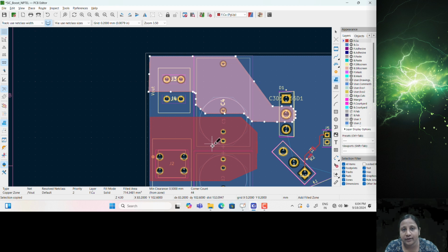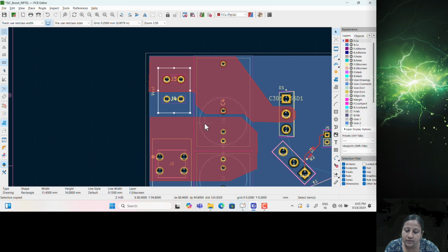In a similar way, the ground reference is connected in this red portion. Here all the points related to ground are connected. You can just use a simple wire or you can show it in the shaded portion, right? The entire red portion here is V out. All the pins belonging to this are connected together. So you can keep it properly and give a particular area for that V out or the ground reference. It will reduce the noise in the PCB.